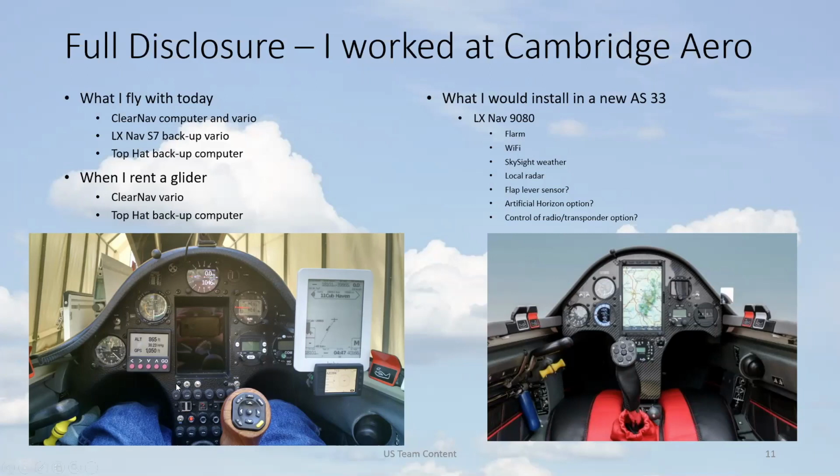And we've got the pictures here. If you can see where my mouse is now, there's the main switch on my panel. Next to it is standby, and next to that is the tail battery. So if I'm losing my main battery, I push the standby on at the same time. Then I've got both main and standby on, and then I release the main, and I've swapped from main to standby without restarting all the computers.